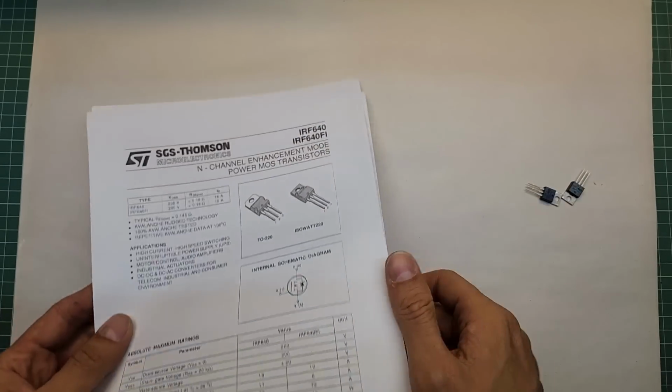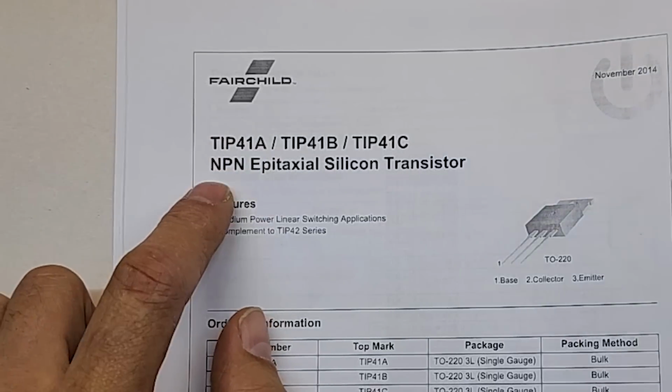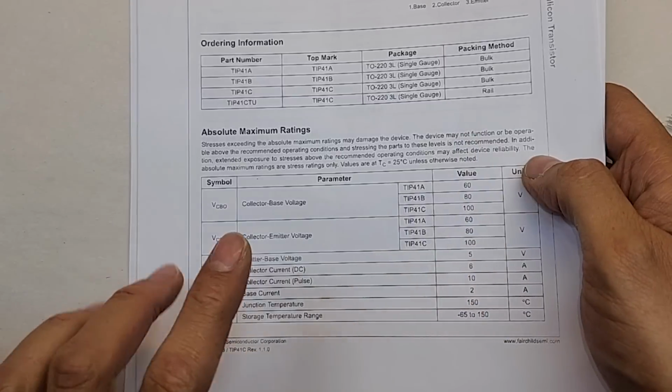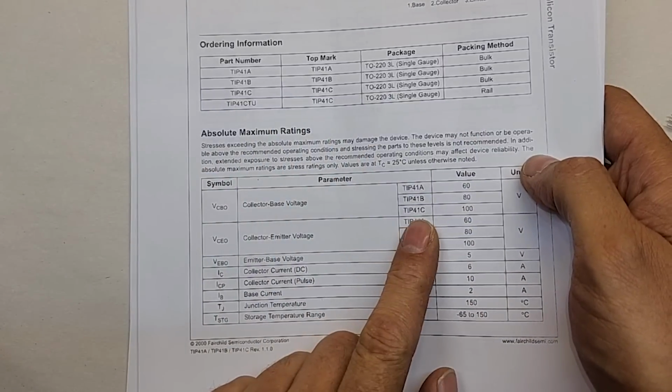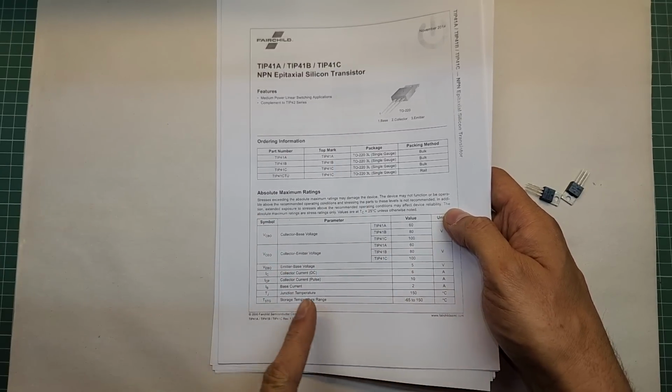For example, both of these are IRF640 MOSFET transistors, but the value of these parameters will be different for each device. Now, this is the datasheet for TIP41, an NPN BJT transistor. Also, there are numerous parameters here, and again, these are not exact values you will face in a real device. Values of these parameters will differ from a device to another. This is called variability, and it is not an unusual thing in electronics. Almost every component has a datasheet, and values on the datasheet are not what exactly you will face in reality.